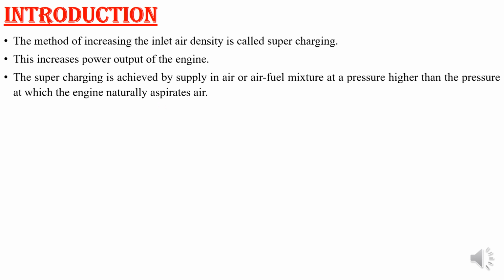If you add a supercharger to a naturally aspirated engine, what will happen? It will increase the pressure of the air. While increasing the pressure, the density of the air or air-fuel mixture also becomes more. That means a greater amount of air can be introduced inside the cylinder. That is nothing but the supercharged engine.